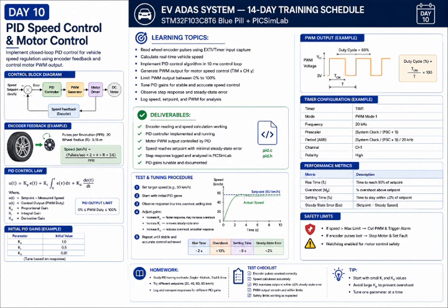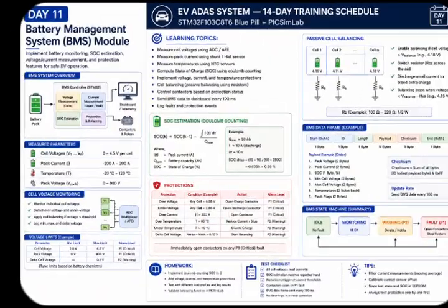And coming to day 10, all modules developed during previous days were integrated into a single application. I tested sensor accuracy, regenerative braking, drive modes, watchdog timers and their operations, and timing performance. The objective was to verify that all components work together reliably.